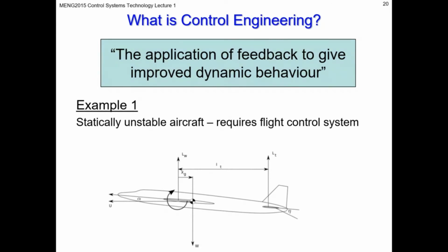Because the aerodynamics is fairly speed dependent, so when a vehicle reaches, say, 50 miles per hour, a spoiler might rise, or a diffuser might close up or change shape, but that would not really be a dynamic response to some feedback. It would just be triggered by a certain speed being achieved. So that would be described as an open loop system.